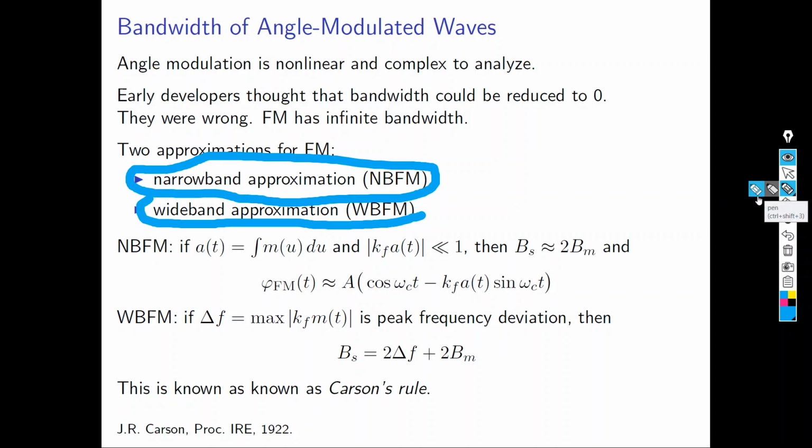You will see that the bandwidth of angle modulation or frequency modulation in general is sometimes infinite, but as the frequency increases, the power of those high frequency harmonics becomes so little that you can ignore it, and that's why you can confine the bandwidth. You can say that the bandwidth can be approximated to a certain value.